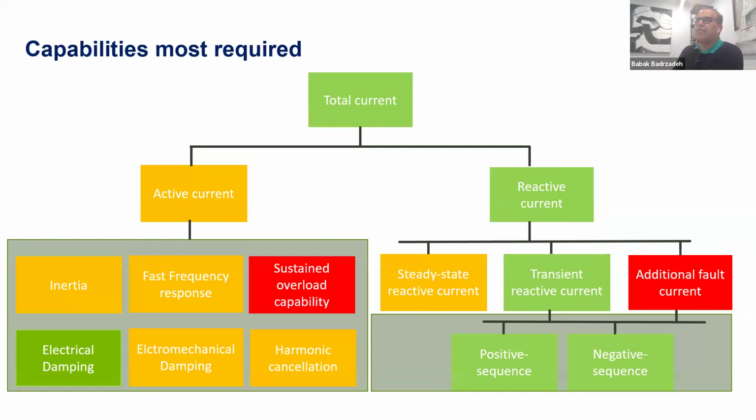Okay, so that was basically a general view, regardless of anything really, for grid forming inverters. Now, the title of this particular aspect was the medium system strength condition, and how I differentiated was that there is very little or no coupling, most often no coupling between the voltage and frequency control. And in this case, I'm saying things like additional fault current.